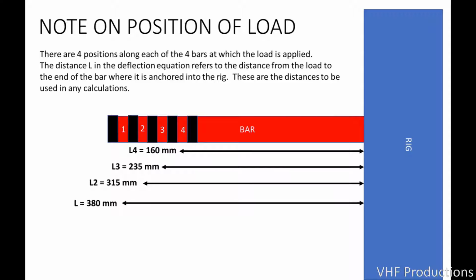We're going to try to correlate the loading position L, where the load is being applied to the beam, and the deflection the beam is experiencing. If we go back to the equation given previously for deflection, we know the deflection is a function of the load and the loading distance. Since the deflection scales with L cubed, changing the loading distance will have a significant effect on changing the deflection. And that's part of what we're trying to test here.